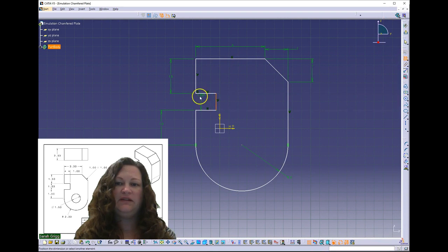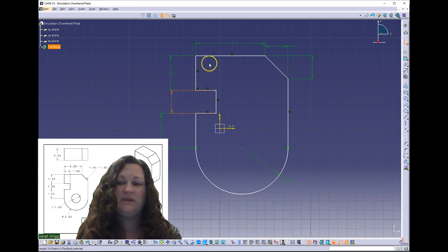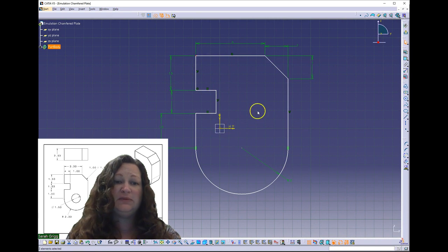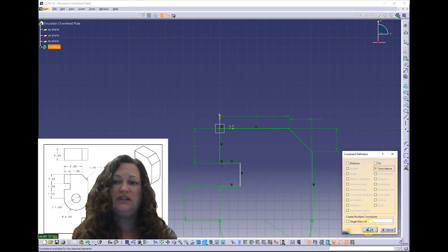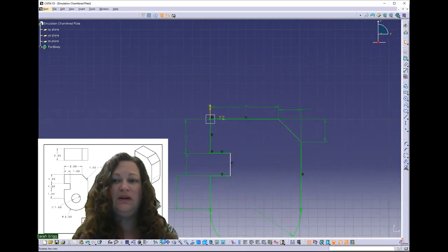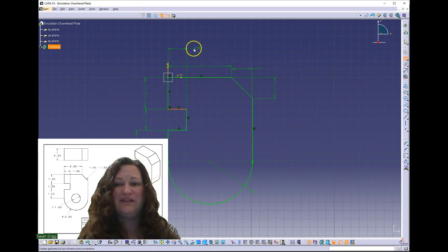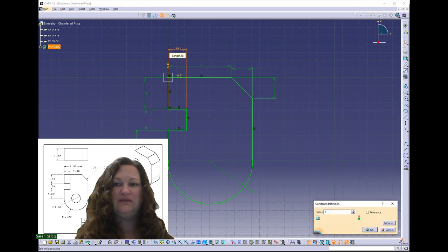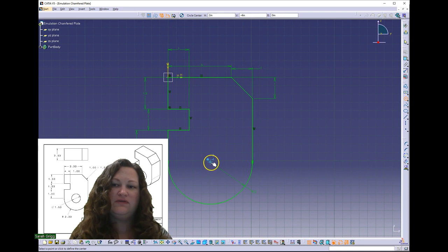Now I'm going to set my locator to the top corner being coincident to the origin. I could have used any point on the object, and I could have done distance measurements of 0 as well. As long as it's located to the origin, it doesn't really matter how. Some ways are easier than others. So that's just a fairly easy use of the locator. Finally, adding my circles.